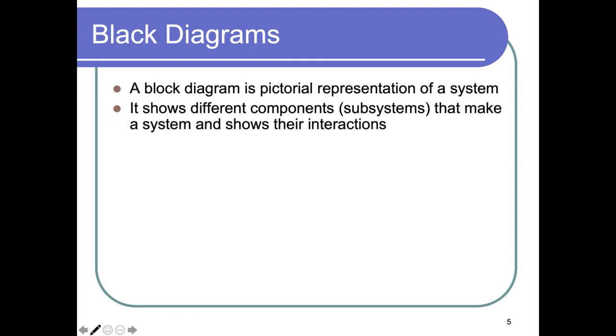But using block diagram reduction, I can convert a control loop with multiple blocks into just one block, where the input to it is the input signal, the reference signal, and the output is the final output of the system. And that block, if I know it in the frequency domain, it's the transfer function, then I can just multiply it by 1 over s and observe the step response. And with that, I can know how my system will behave for a given input. And then based on that behavior, I know if my system is behaving well or not.